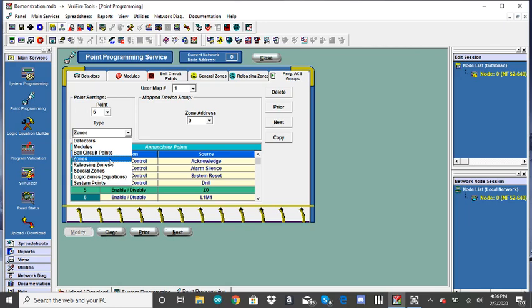From the fire panel, you can have remote CO sensors throughout the building, and you can put those carbon monoxide sensors on a monitor module, and whenever the carbon monoxide alarm trips, it will trip the monitor module, tripping the panel. Now, you don't want a carbon monoxide detector tripping the fire alarm. You want it to trip the carbon monoxide system. So you give it a different software zone. Let's say you program it for software zone 13.